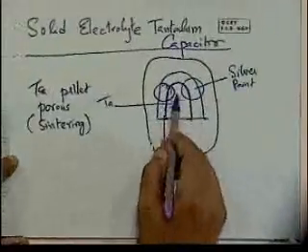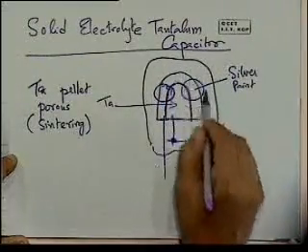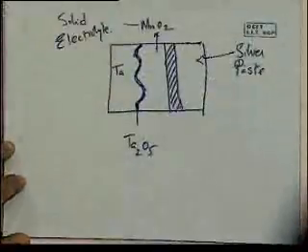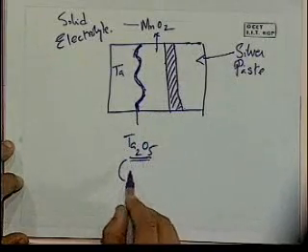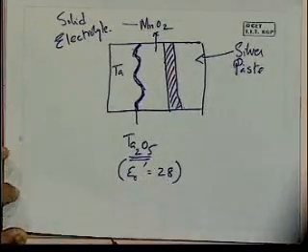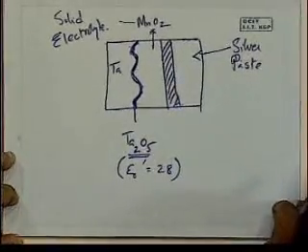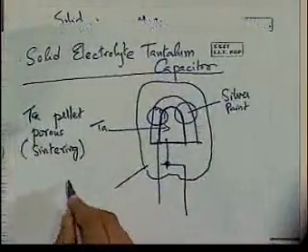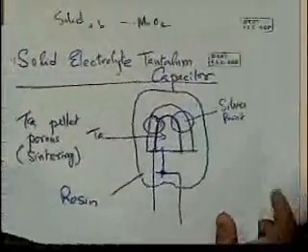So this whole thing is again, this one tantalum pellet, and this whole layer here consists of 2-3 layers. I haven't shown it. What we have just shown is one layer there, silver paint, is really consisting of smaller layers which have been blown up here. The real dielectric medium in this case is Ta2O5 again, with a dielectric constant of roughly 28. And the outermost packaging that we use here is also some kind of organic resin. So it's encased again to protect it from moisture and dust.